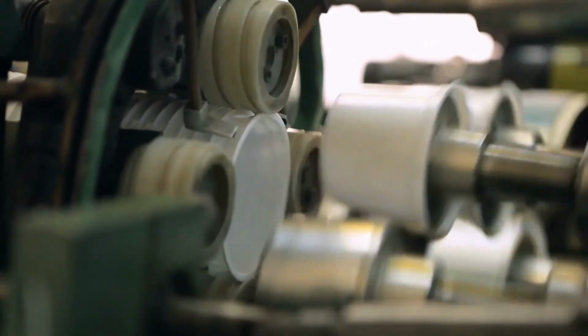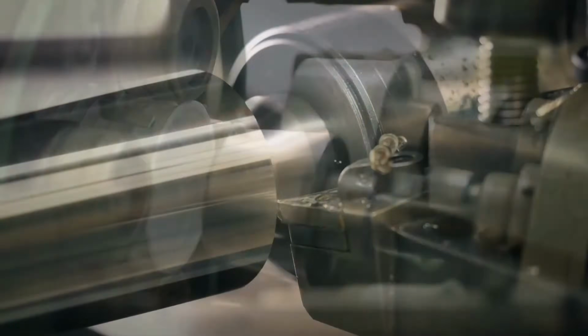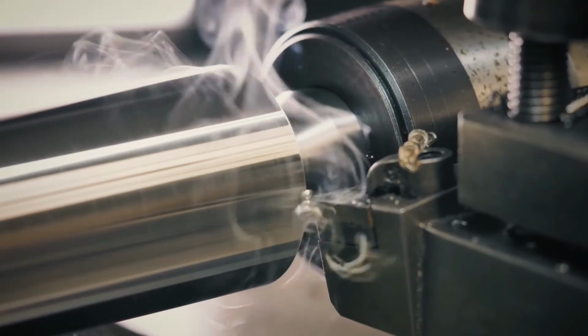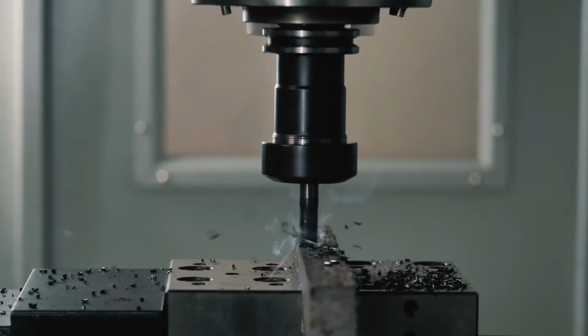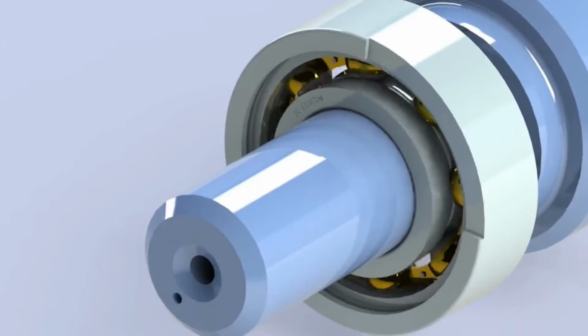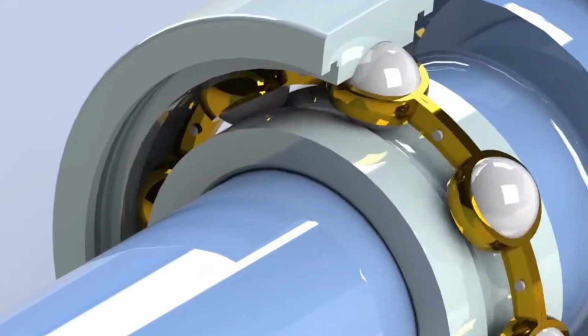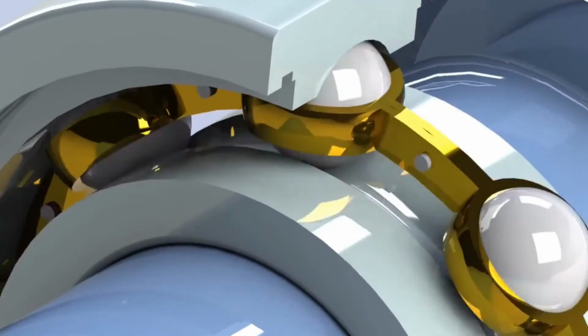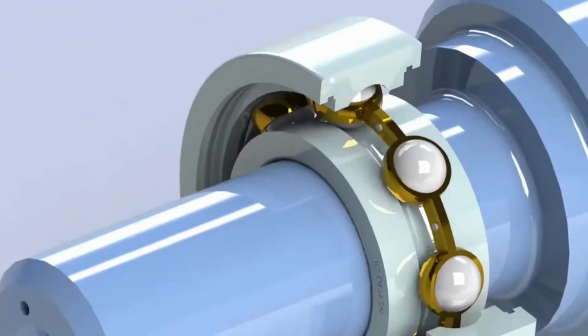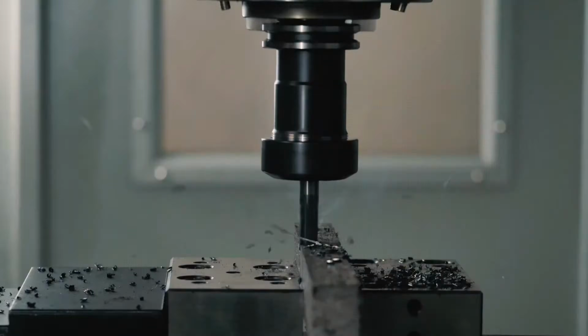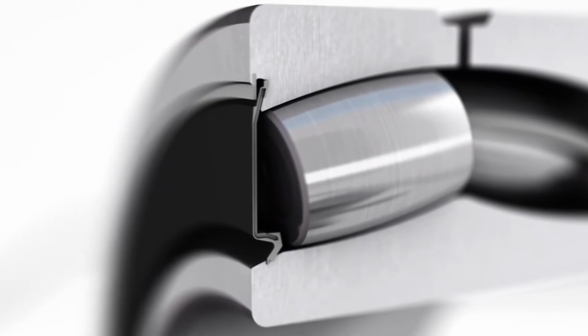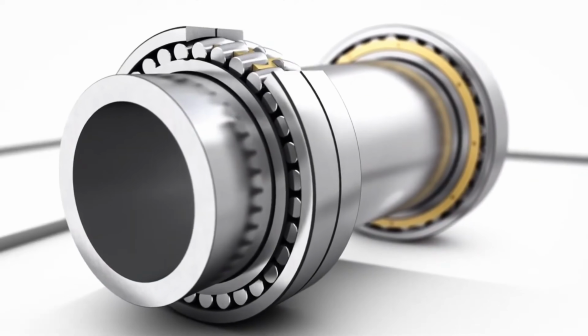Bearings played a pivotal role in the nascent Industrial Revolution, allowing the new industrial machinery to operate efficiently. Bearings are one of the simplest yet crucial machine elements. The main purpose of bearings is to prevent direct metal-to-metal contact between two elements that are in relative motion. This prevents friction, heat generation, and ultimately, the wear and tear of parts.